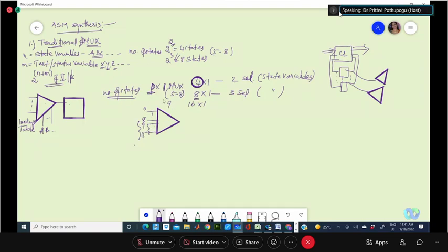If your original ASM is having, say, 9 states, we are in need of a 16:1 mux. And this 16:1 mux has how many selection lines? 4 selection lines. Out of this 0 to 9, your original ASM will already be using. The remaining are vacant for us.